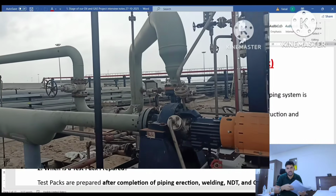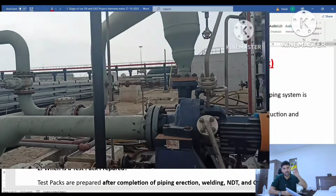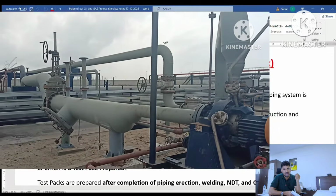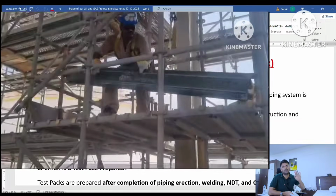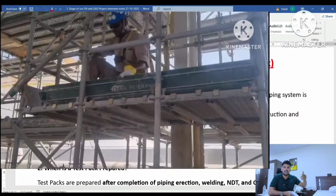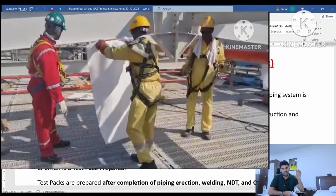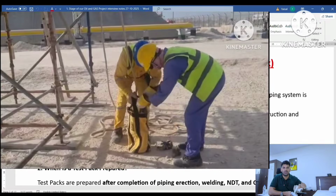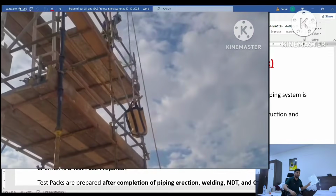On behalf of this record, it ensures the system integrity, that it confirms the piping, fittings and welds can safely withstand the design pressure, that welding is completely done, and that this joint, this welding point or this flange joint can withstand the design pressure without any leakage or deformation. That's why a test pack is important.